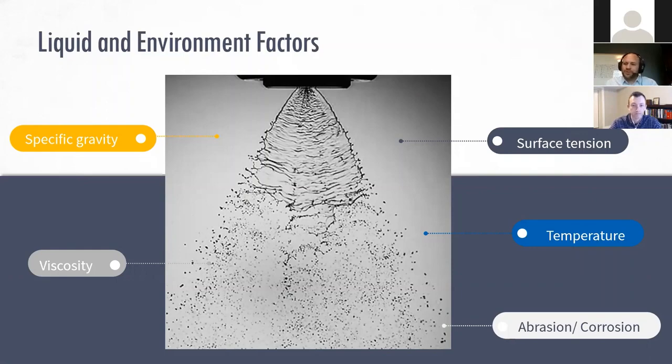And what we've observed in the lab and in the field is the impact that viscosity and temperature together have on spray pattern. And then you talk about transfer efficiency, then you have misting and all of these unique things that happen when you collapse that spray pattern. It's a lot of opportunities for optimization with the more information.